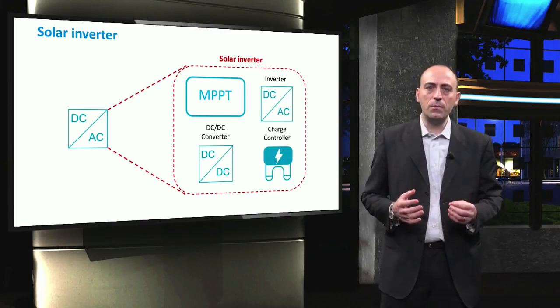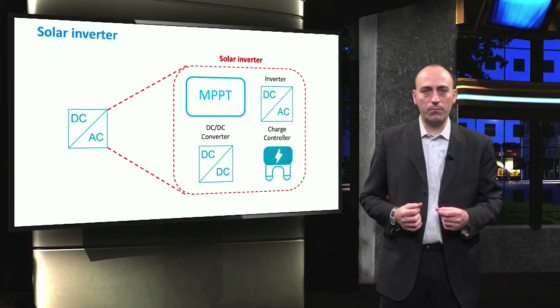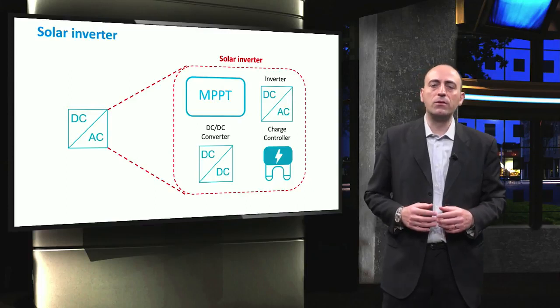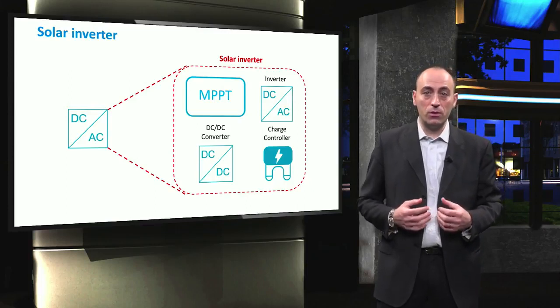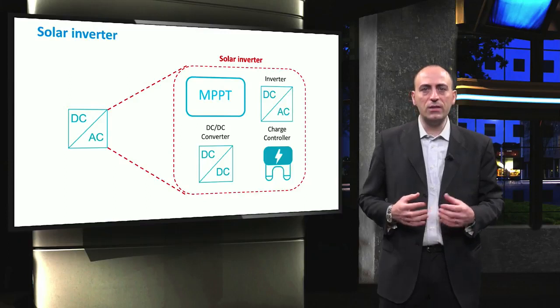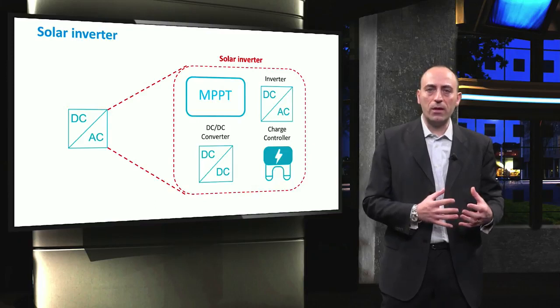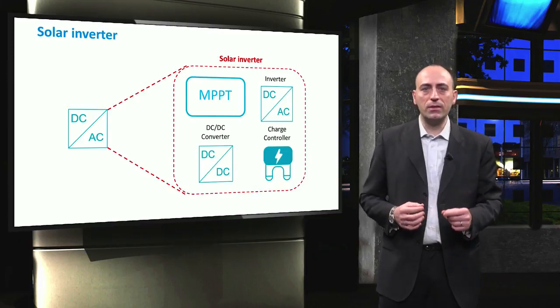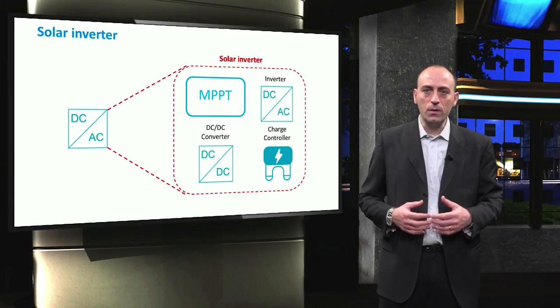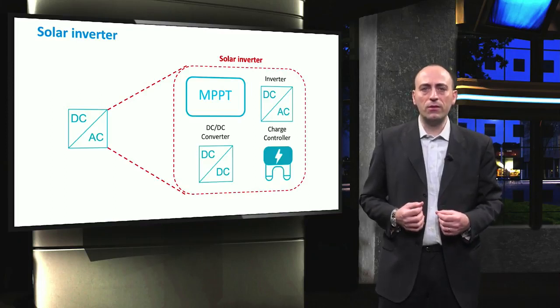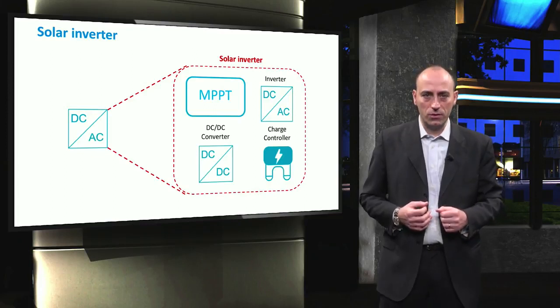In an inverter, DC power is transformed into AC power. Generally, the DC input voltage of the inverter must be constant. However, the maximum power point voltage of the modules is not. Therefore, a DC-DC conversion stage is used to transform the variable voltage from the panels into the constant voltage required by the DC-AC inverter. While the constant output voltage is achieved by means of a feedback loop, the desired operating point of the PV array determined by the MPPT algorithm is used to control the duty cycle of the converter.